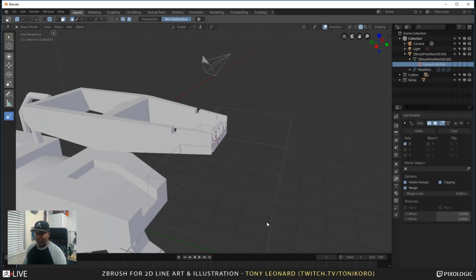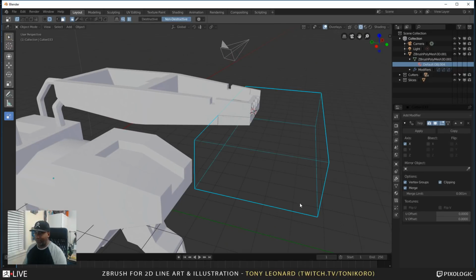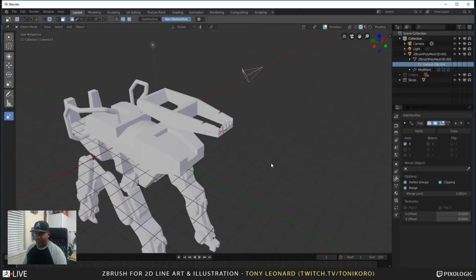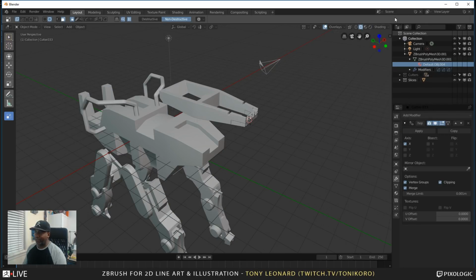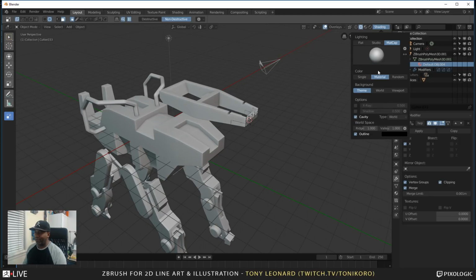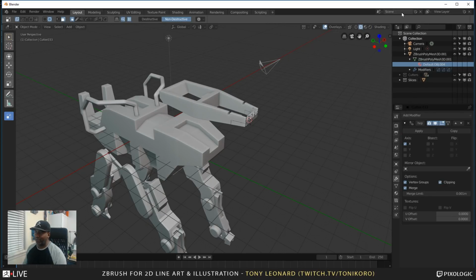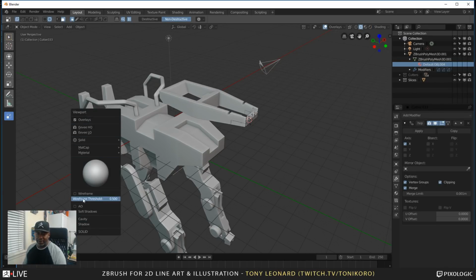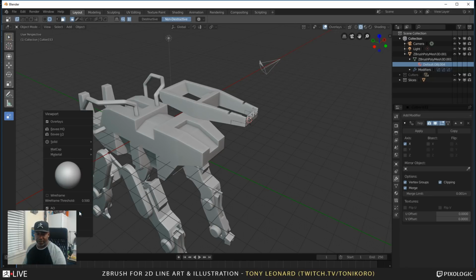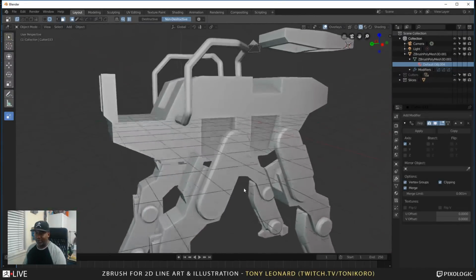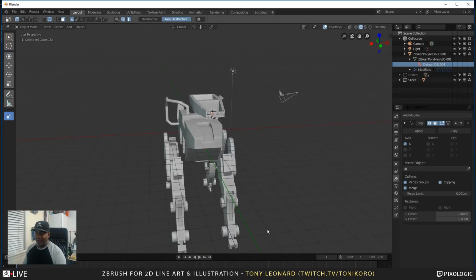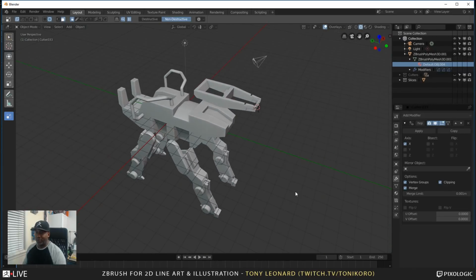And then also, of course, because a lot of the stuff that I'm dealing with here in Blender is real time, go ahead and hide this. I'll go over to my shading and I'll just grab a matcap and put that on there. Maybe we could have a better view of some of our shapes, because it's got shading on it. Shadows and AO can be applied. So if you hit the Alt V key, a lot of times you can hit AO and soft shadows, and of course we can see with a little bit more clarity a different material without bogging the system down with something like a rendered view.